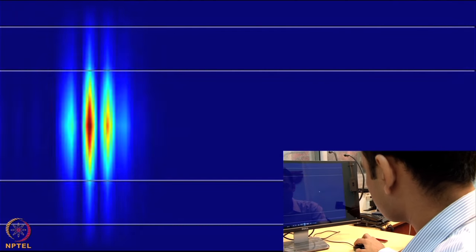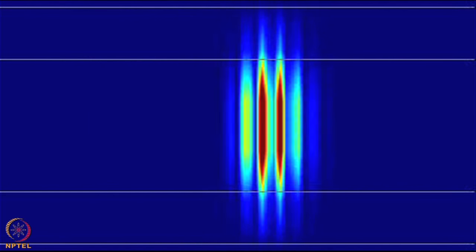So go a little bit finer in the discretization. If you have more cells per lambda. This example was for lambda by 3. So if you have more cells per lambda, this is for lambda by 5. So we can see the mode a little more clearly as compared to lambda by 3.